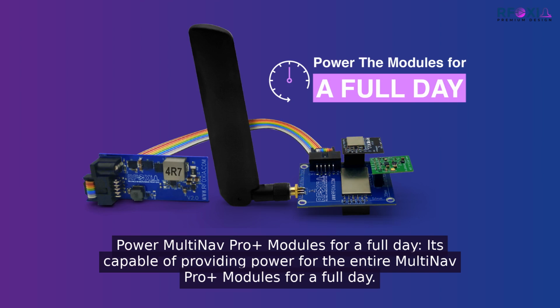This is the complete module stack running on a single charge: BLE module, GNSS module, sensors module, all drawing from the same power bank simultaneously for a full working day. When you are doing firmware development in the field or in a lab without a reliable bench supply, this matters. Your programming environment, your target device, and your sensor stack all share the same clean, stable voltage source. There is no mixed ground problem when everything is on the same isolated rail.